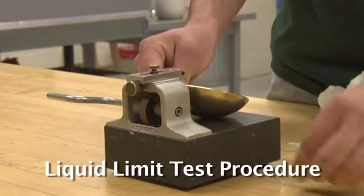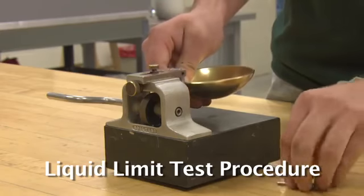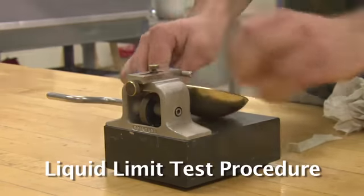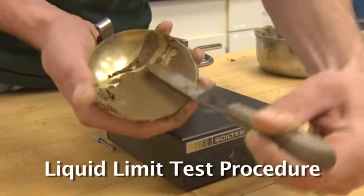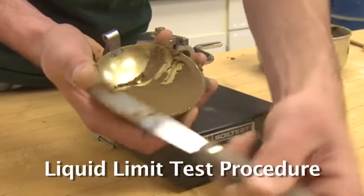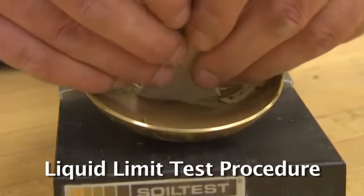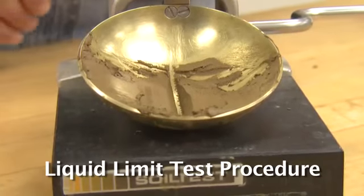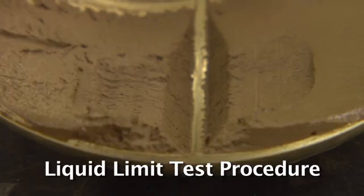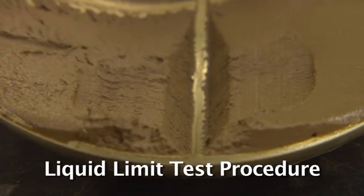Thoroughly clean and dry the cup. Evenly spread a moderate amount of soil into the cup to create a soil pat to be tested. Using the grooving tool, create a straight groove through the center of the soil pat. The shoulders of the grooving tool should just scrape the surface of the soil pat. If the shoulders do not contact the soil pat surface, too little soil has been placed in the cup and the test should be restarted.